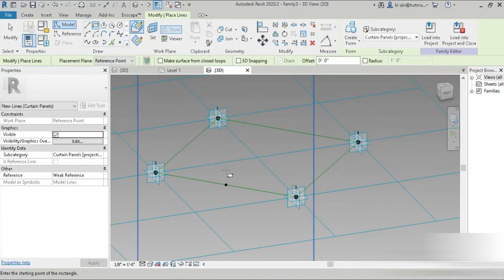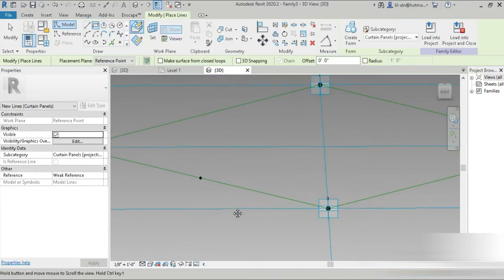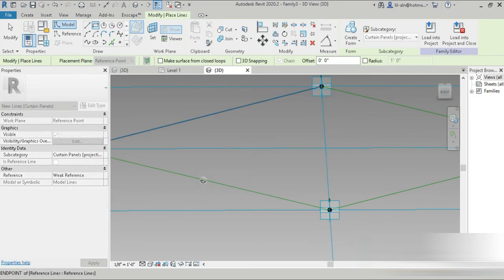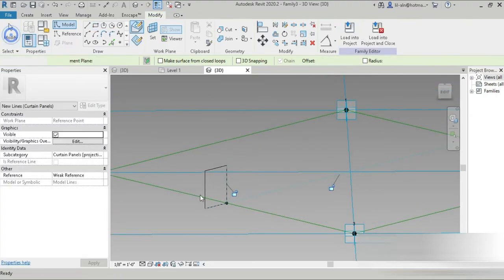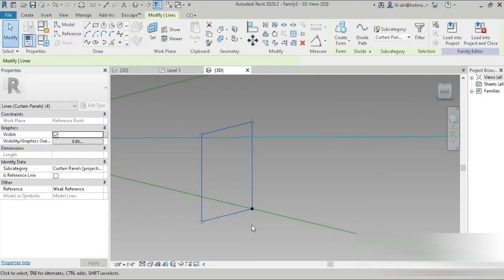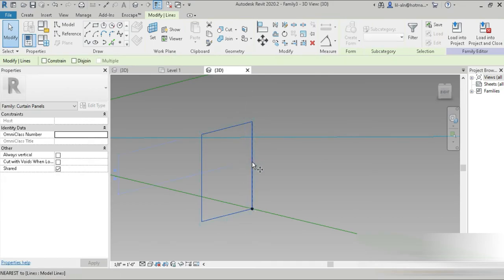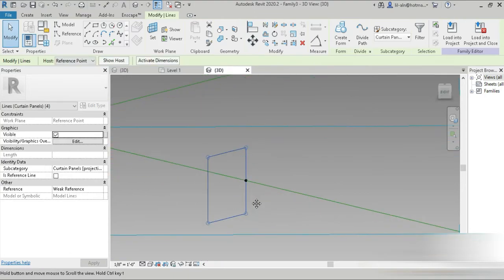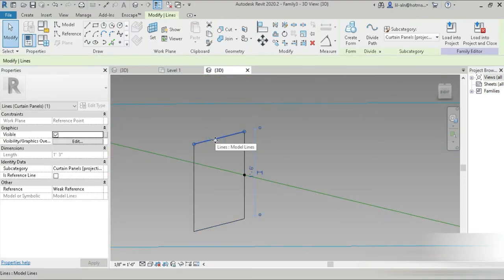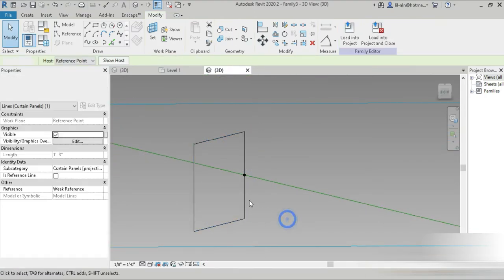Now, if you go to Rectangle, can we make a rectangle right here? Yes, of course we can. Select this and use MV to move this down right here. Okay, done. And of course we have to make it adaptive.